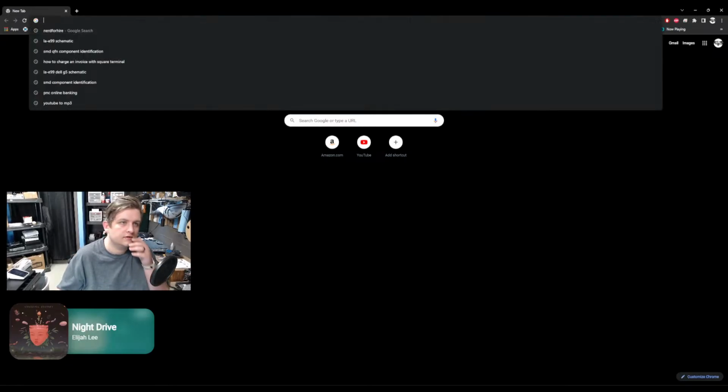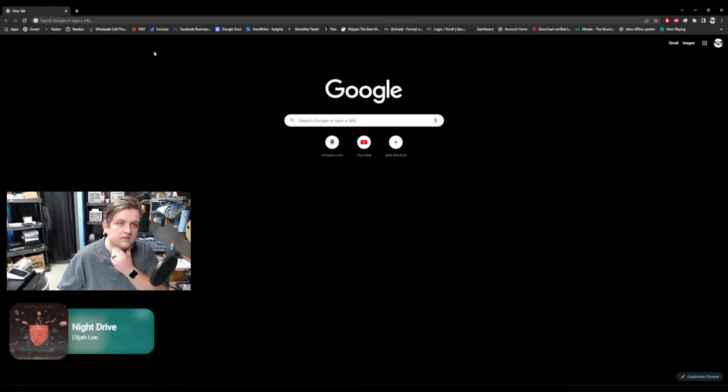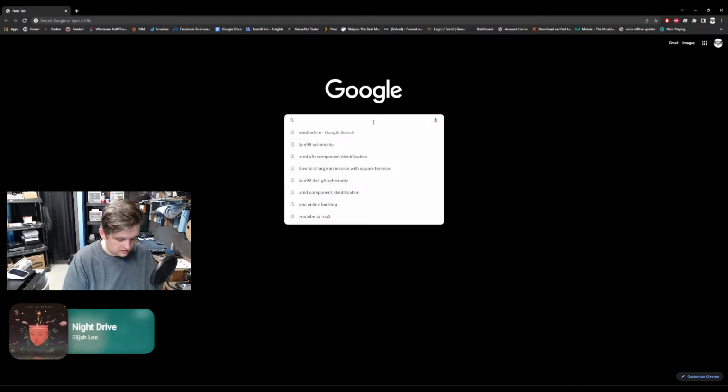So, first thing we're going to look for is trying to find easy charts or something to get that QFN chip pulled up. A picture on my phone is how we're going to look at it. We're going to find a schematic first, because if we find a schematic, we might be able to identify the chip easier.